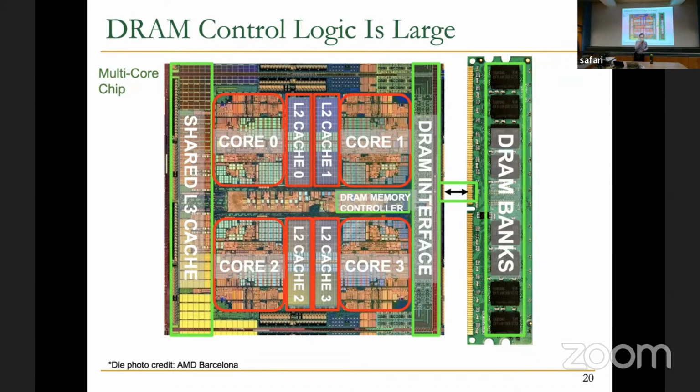We discussed actually one idea when we talked about RowHammer, the self-managing DRAM idea, right? That's kind of dividing some of the responsibilities of the memory controller between the processor chip and the memory chip, saying that management functions that DRAM designers are intimately familiar with should go into the memory chip, inside the controller over there. And the memory chip should have breathing room provided by the interface so that it can actually perform those management functions. So that's one example of reconsidering the design trade-offs.